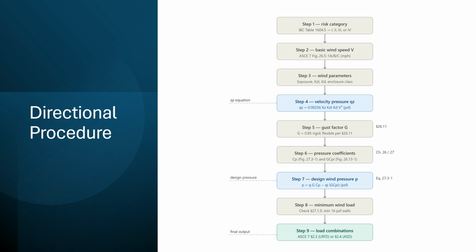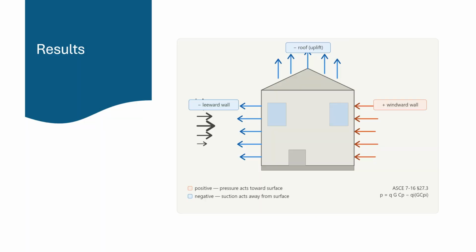And then your final kind of deliverable will be your minimum wind load plugged into your load combinations for your design. And most of the time, this is idealized as a line load on the diaphragm of each of the corresponding levels to the height of the structure. But there are different ways you can do it.